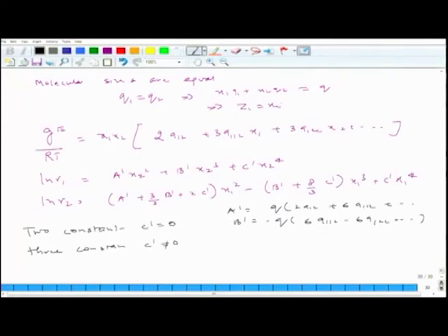So, the Margules equation for 2 constants and 3 constants has a basis of molecular sizes being equal, and it is derived from the Wohl's equations. In practice, the 2 constant and 3 constant Margules equations should not be used for systems having dissimilar sizes, but in practice they are also used.